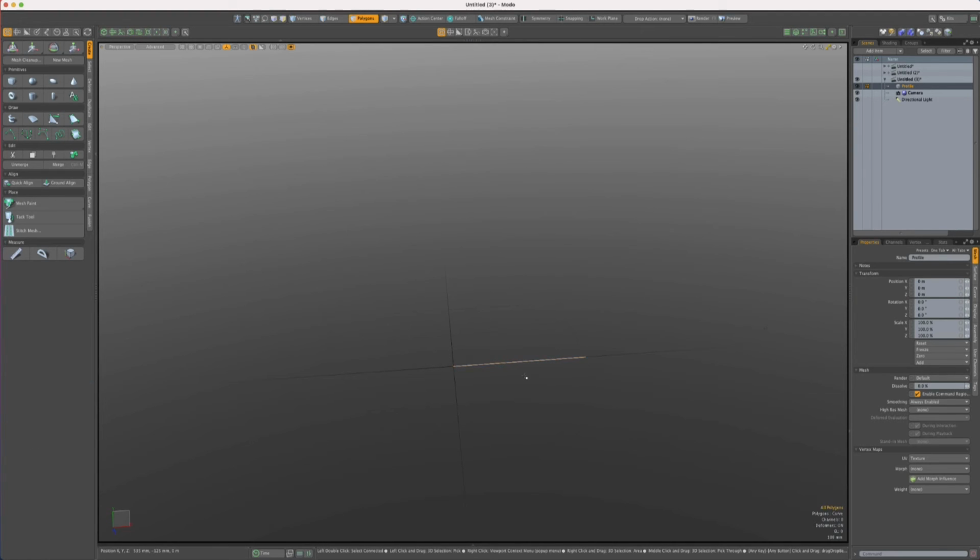So when you select it, it will activate the curve tool, which will allow you to edit the points if you wanted to. And you don't need to drop a tool before you activate another tool. So I'll just hit R to activate the scale tool. The tool handles come up in the middle of the curve. They'll always come up in the middle of the geometry if no action center is activated.